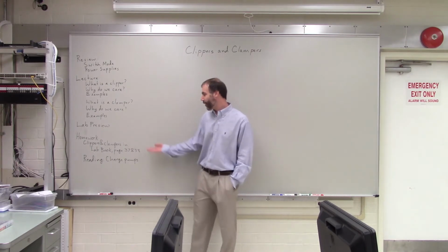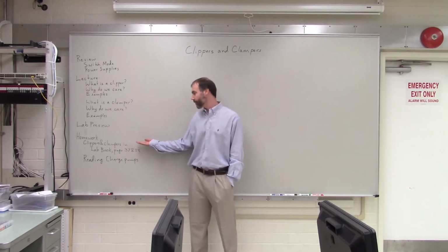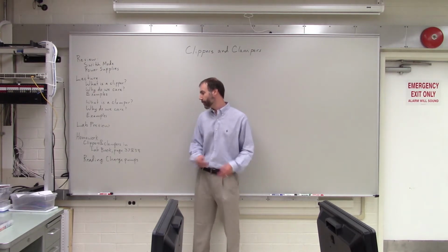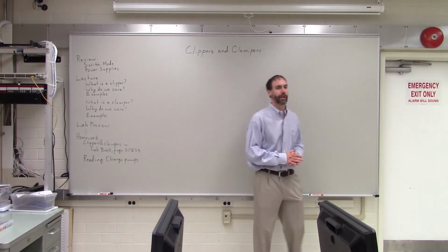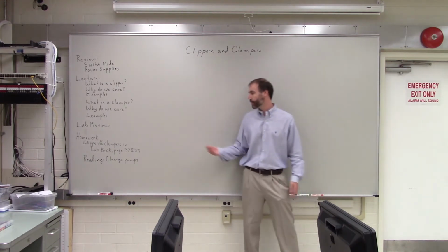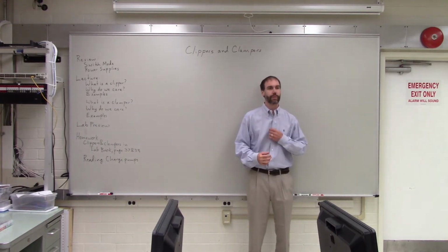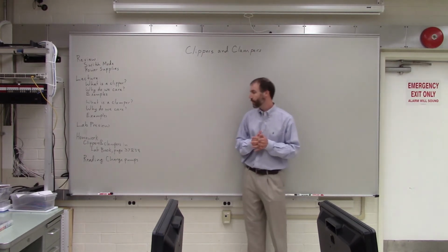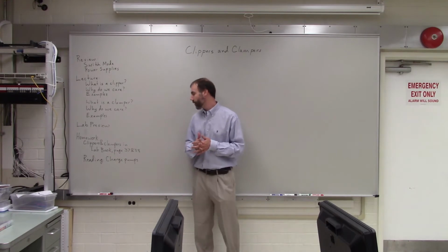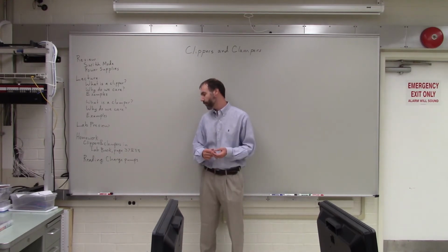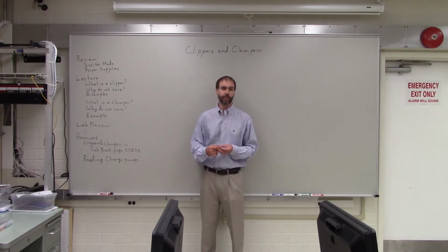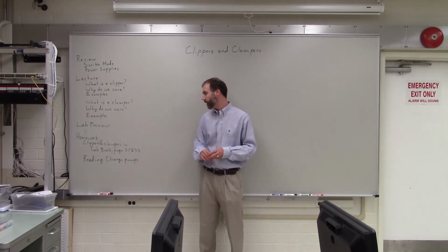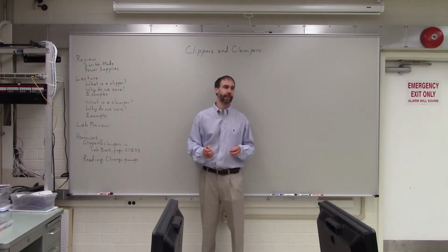All right? For homework, there is a couple pages in the lab book that have examples of Clipper and Clamper circuits, and they ask you to figure out a couple things about those. Those are on pages 37 and 38. So you guys can get started on those after the lab tonight. And then if you have any questions about those, or if you want me to do one or two examples, maybe we can look at one example tonight, and then if you have questions about that,